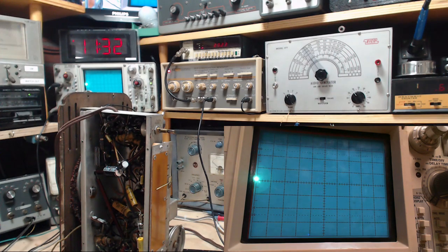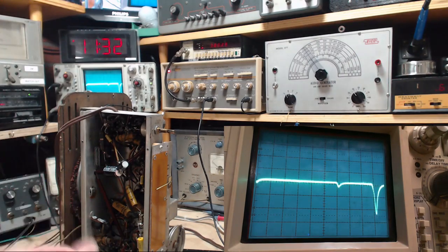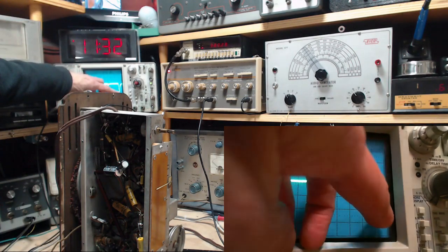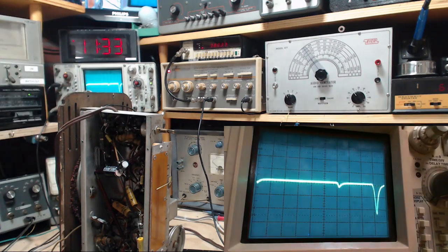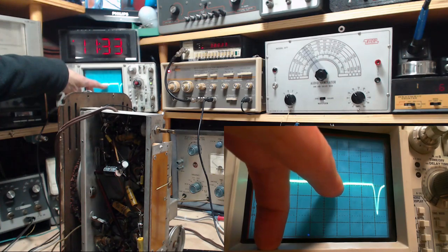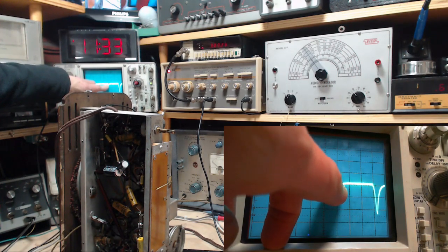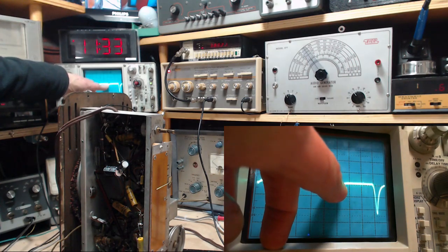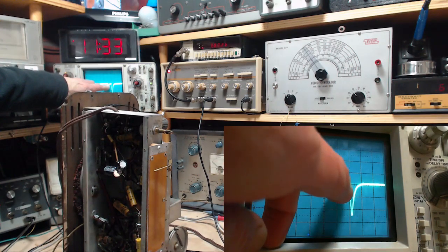Think about this. What are we actually seeing on there? Let me turn the sweep back on here. So, what we're hearing coming out of the speaker is certainly this thing. Are we hearing this thing too? Is this generating a small AVC voltage? You know what? I can figure out what frequency that is. How do we know? By tuning the radio. I already know it's... I think it's 455. I'm going to guess.